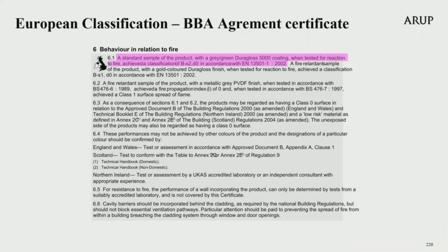Finally, the European classes were referred to regarding the Grenfell Tower primary refurbishment external wall products. Only one product installed on Grenfell Tower was presented as relying on the European classification system, and this was the Renobond 55 PE panel. Celotex did not test their insulation to the European tests until after the Grenfell Tower fire.